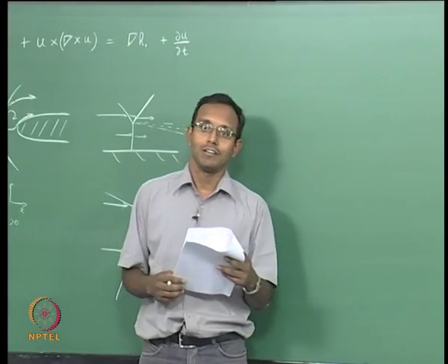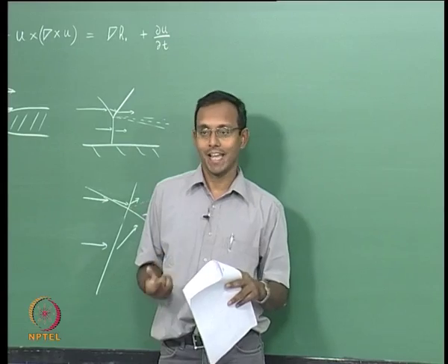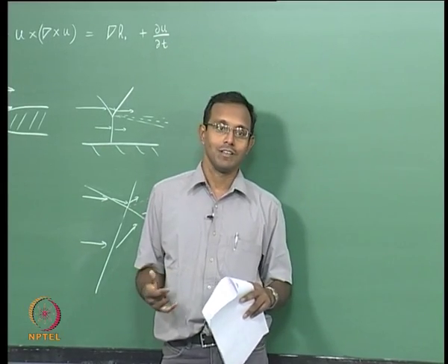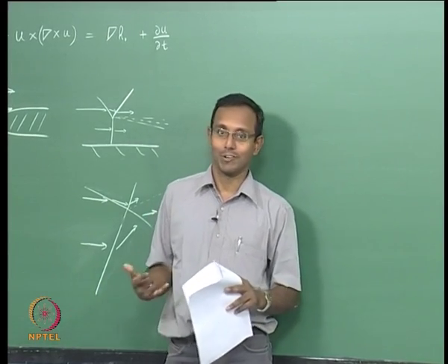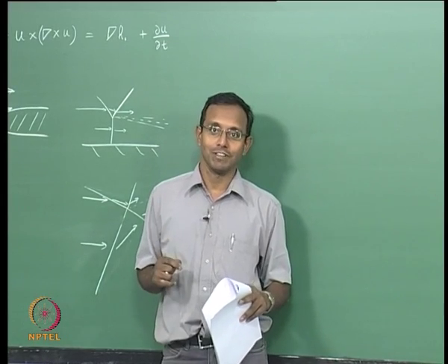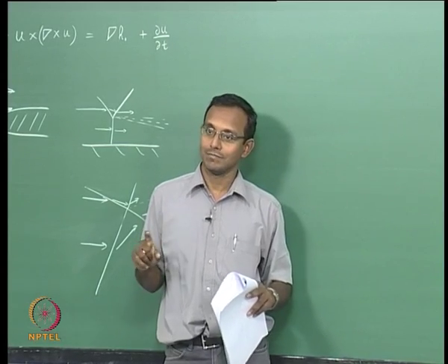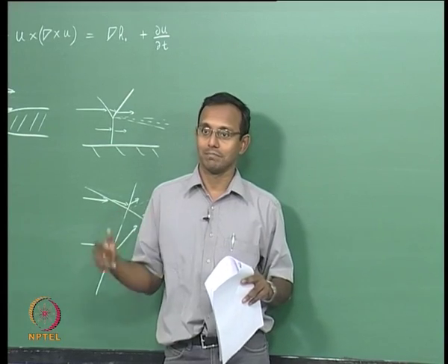We will just move on to adiabatic flow in a duct with friction present. I am saying adiabatic flow in a duct because I can also solve a problem for isothermal flow in a duct, where the temperature of the wall is fixed or the temperature of the gas is fixed. I can work on any particular way where heat transfer is allowed. We will currently work with a situation where there is no heat transfer into or out of the gas. Whatever stagnation enthalpy the gas has, it stays the same.